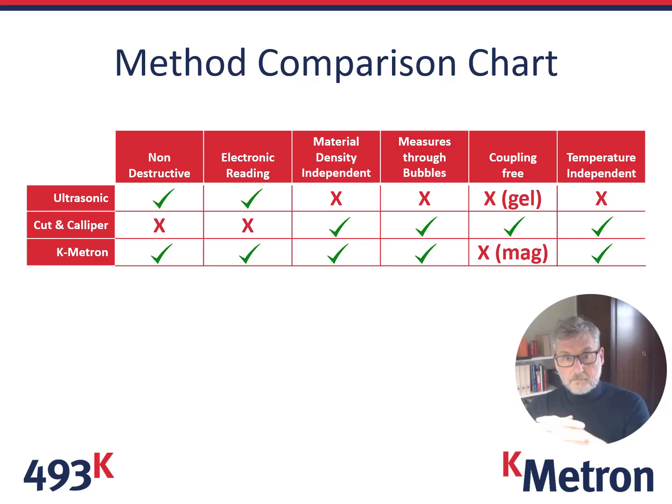And the second, more destructive method is to cut the part up and to use vernier calipers to measure the wall thickness. Obviously, once that is done, the part cannot be used. Worth noting that measuring of parts by this method, cutting and caliper, cannot be used for parts which are perhaps going to be submitted for standard tests at a local laboratory.